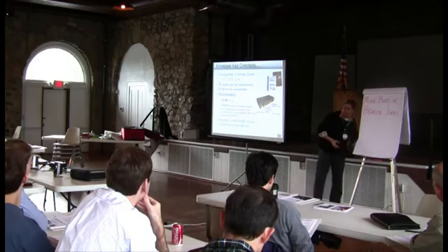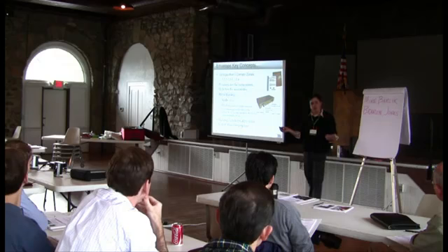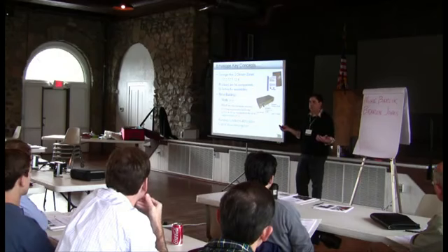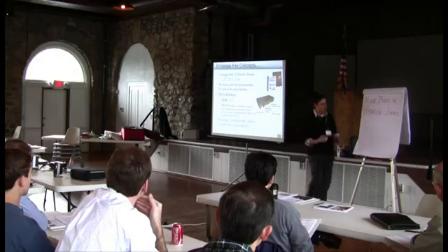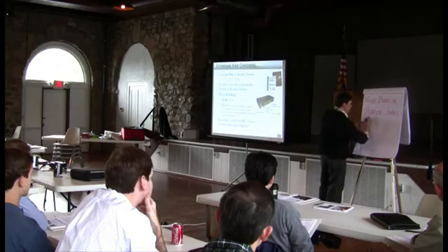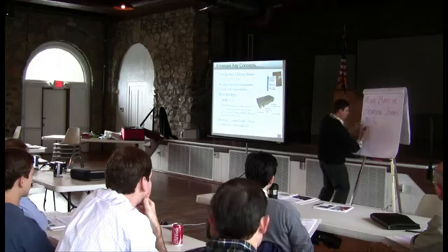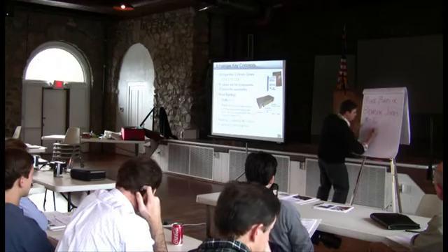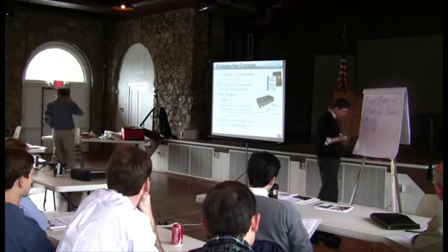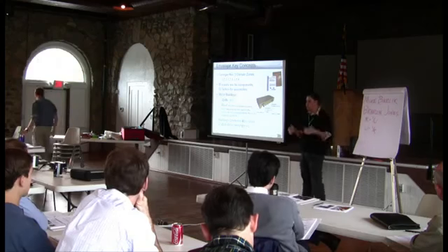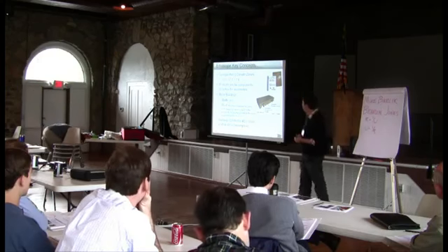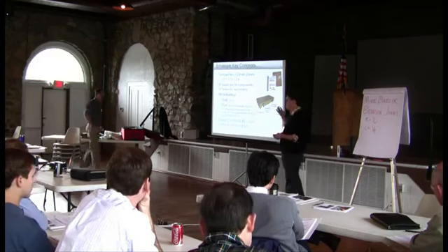What about U values? What is that? It's the reciprocal, the inverse. So R value equals 1 over U. Conversely, U equals 1 over R. Now, they use R values, this resistance, really for materials or components.